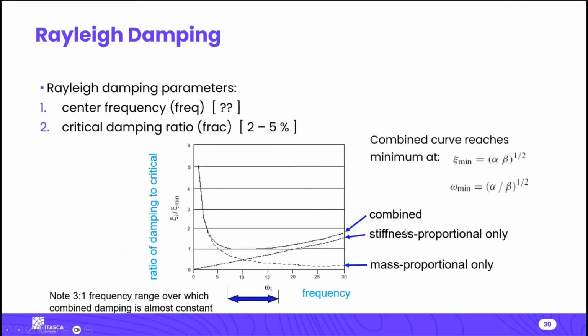You don't necessarily have to understand all the math. You just need to know that if you're using it, you need to specify some frequency, because what it will do is it will try to work out the components here so that you have a flat response close to that frequency. So this can potentially be a challenge. I mean, in our case, it's easy. We're putting a wave through with 40 hertz. It might not always be that easy to figure out what your frequency is. I'll show that on the next couple of slides.